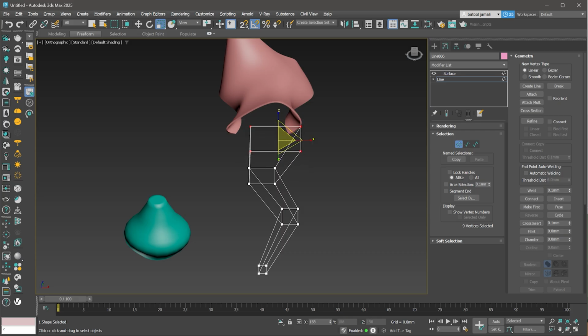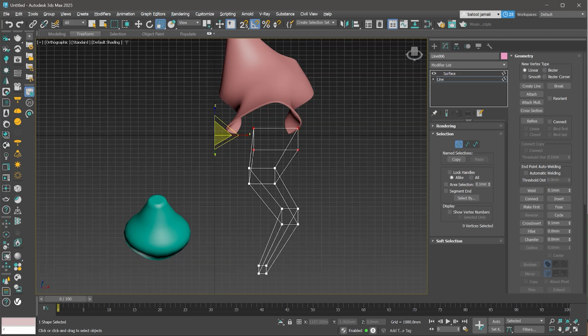and then I can scale it down this way. Now, again, this is something that we've already mentioned in the previous semester. So you can change the pivot point location. Either you can put it in the selection center, so it's in the center of everything that you've selected, or you can make it at the pivot center. So for each one, it will move according to which one you are scaling, and it will scale each one individually. And then this is according to the center of the grid.